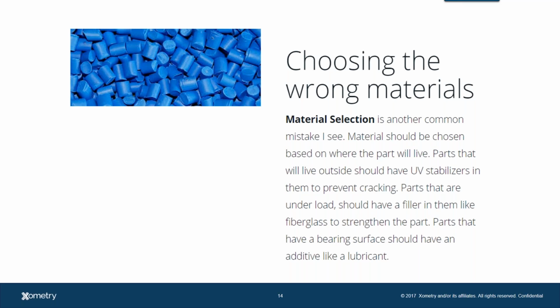And once you press go and you commit to that tool, it's very, very hard to change a family of materials because we are compensating for the shrink rate of the part. We're compensating for certain deflections that may be happening in the part within the tool design. So going from a very stiff, well-behaving plastic like an ABS to something that's a little bit more mischievous like polypropylene may require a brand new tool to do. And it's just something to understand up front. A little bit of research, a little bit of identification on what you need will go a very, very long way as we talk about production of parts.